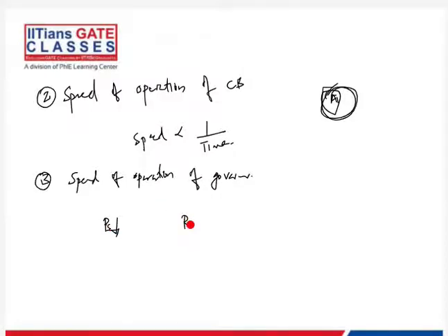PA is equal to PS minus PE, so if PS can be reduced, PA also will be reduced. A really good governor can adapt pretty quickly with respect to the fault. Nowadays we have speed governors that are based on electronic devices so that it's faster.